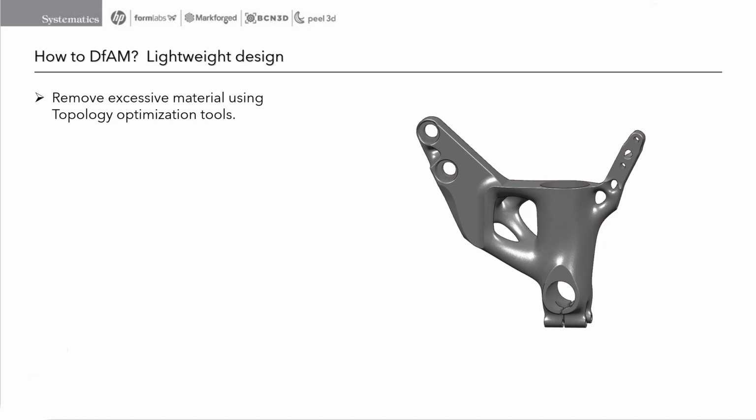Topology optimization is another powerful technique for DfAM that uses computational methods to generate optimal part design. This technique starts with a virtual model of the part and then uses algorithms to determine the optimal distribution of material within the design. This advanced simulation tool can be used to optimize part geometry for specific requirements, to create a part that can perform the function of multiple components.